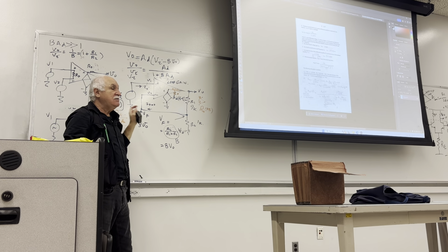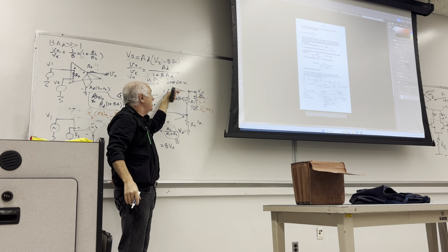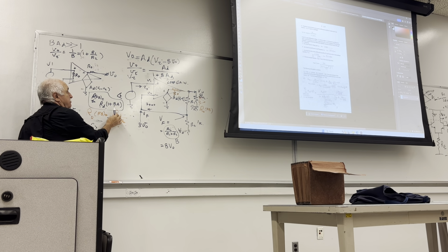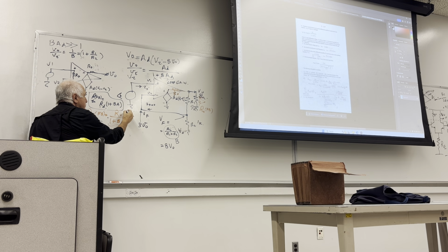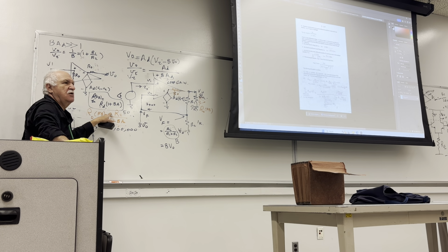And that is why when you connect amplifiers of that kind to speakers of only 8 ohm or even less, it wouldn't matter, because the feedback will make the output impedance from your amplifier look like milliohms. Very, very small, this one. So if that is like 50 ohm, and that is 100,000, the output is only a fraction of a milliohm.